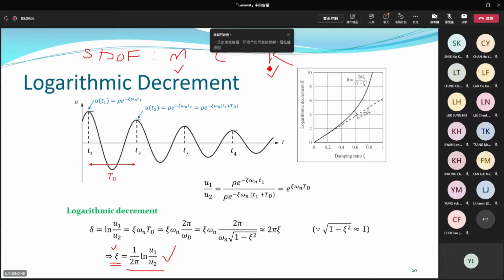K depends on the stiffness of the members: the size of the beams and columns, the elastic properties, etc. I did not mention C actually. I just mentioned that it's related to energy loss, but I did not tell you how to calculate C. This page fills that gap and tells you how to calculate damping.